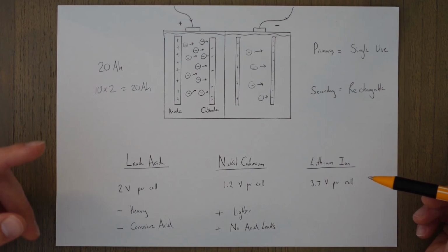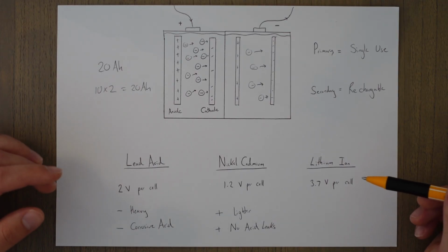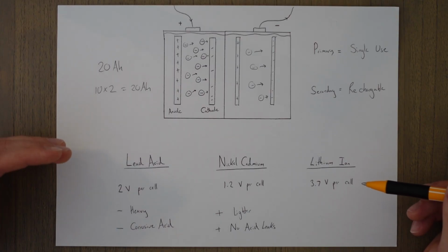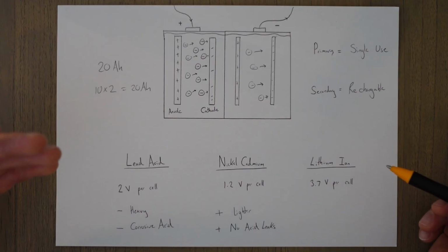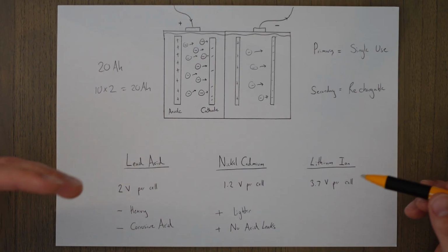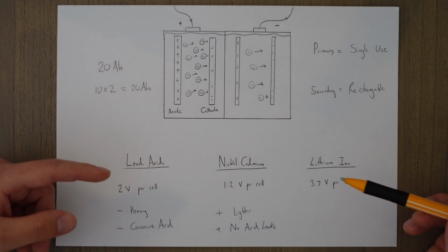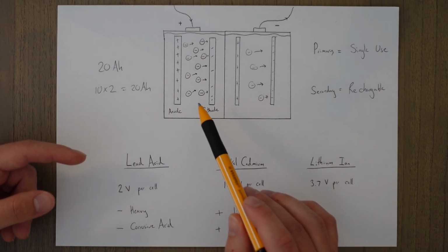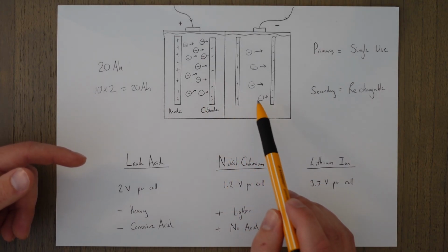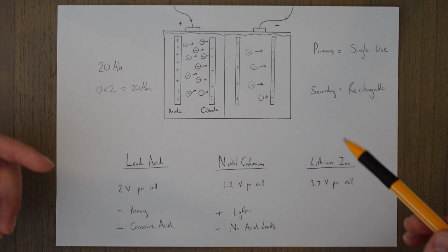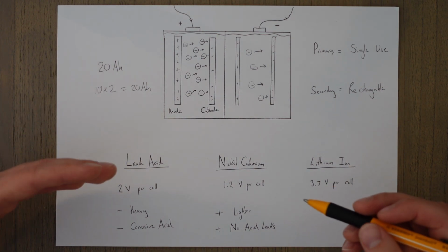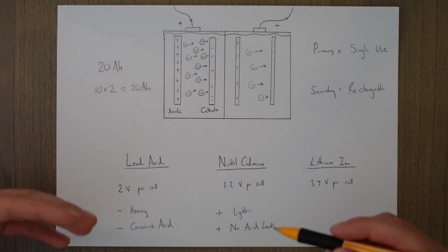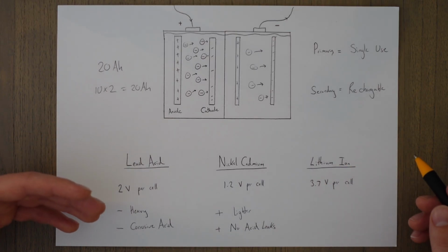They do, however, suffer from a phenomenon called thermal runaway. This is where the cells in the battery essentially overheat, which is mainly going to happen during recharging. The runaway element refers to the fact that only one cell on the battery needs to overheat, and then it overheats the next one, and so on and so on. And this leads to the fire that can sometimes be caused by a thermal runaway situation to potentially keep burning for a very long time.